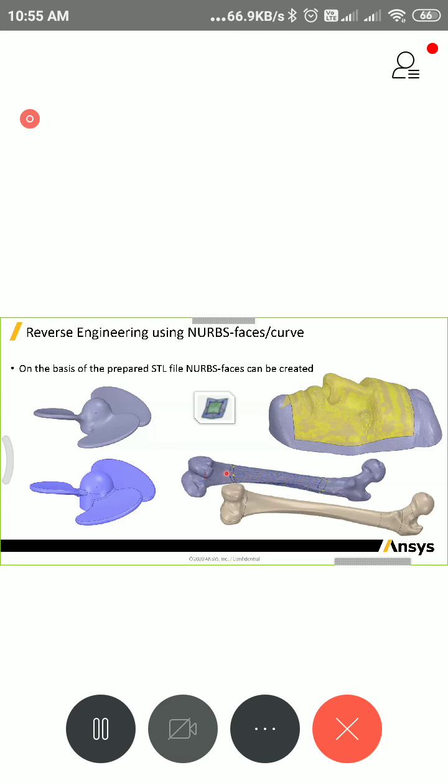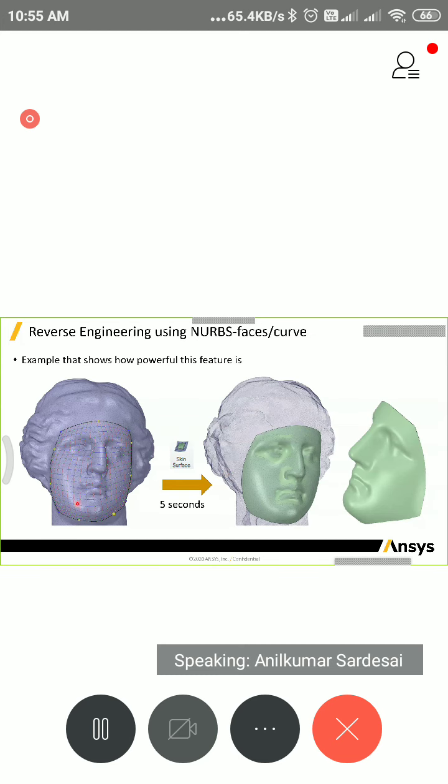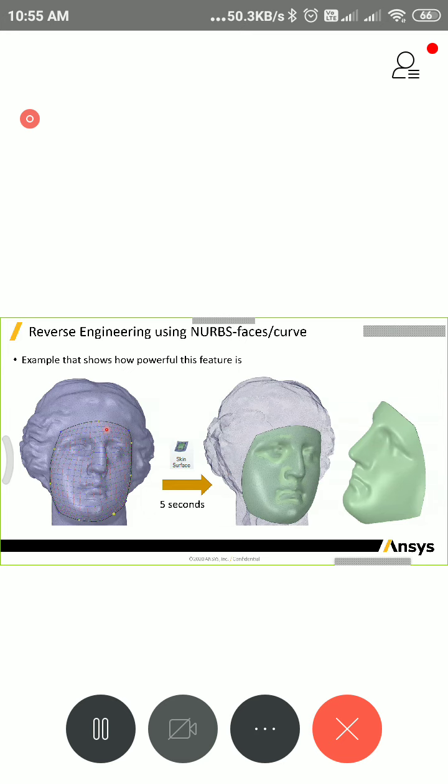So it's very easy and quick. You have the spline surface, you create some patches, and where the patch overlaps your faceted data, you'll get the CAD within some seconds. But this process is still a little lengthy because right now I'm just creating this patch, but I might need to create different patches to take the complete shape of this particular geometry. And sometimes, as your geometry is big and complex, it may take a little while to decide which location you want to start, how you want to patch the next patch, and how you want to connect that.